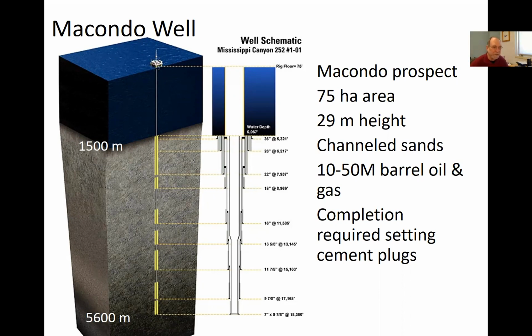When I say drill, what they do is they have a giant motor which is turning a drill bit, and then they have lengths of pipe, drill pipe. Each length of drill pipe is 20 feet long, and so they're constantly adding new 20-foot sections of drill pipe to the top of the array here, and then 20 feet by 20 feet, the drilling is extending down and down and down, all the way down to 5,600 meters below sea level, and about 4,100 meters below the seabed.